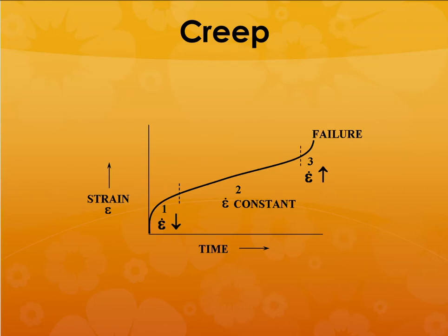I do not know if you remember what you learned in your material science ENSE 3313 course about creep, but what is creep? Creep is the process by which a material will deform at elevated temperatures as a result of a constant stress. Depending upon the stress, it will deform, and once the deformation goes beyond a certain limit, it will fail and it can fracture.